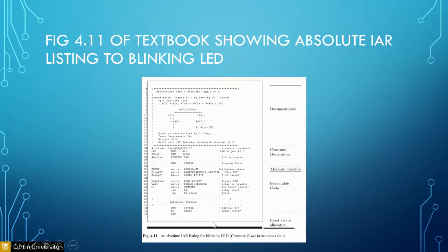If the question asks you what this part does, basically you're allocating the reset label to this address. This is a reset address. So the computation cycles, fetch, execute, and all this, the 3 states, always start with FFFE. So anything happens, it will go there. I hope that after this lecture, you'll be able to understand this section of the code better. All right, labels, mnemonics, operands, and these are commands. Can you operate without the labels? You can, but you need to know the location of the instruction.